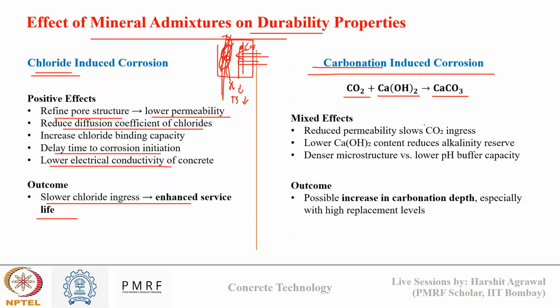SCM addition has mixed effect on this. What happens when this Ca(OH)2 is consumed? The pH of concrete decreases. Once the pH of concrete decreases, the stable passive layer which is there over the steel surface breaks down. Now why do we say SCMs have a mixed effect?